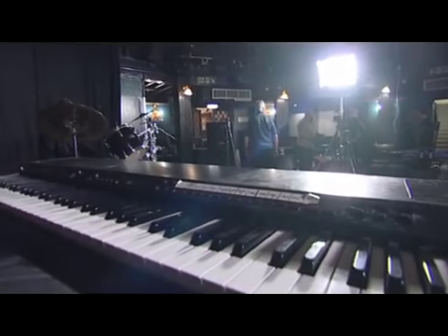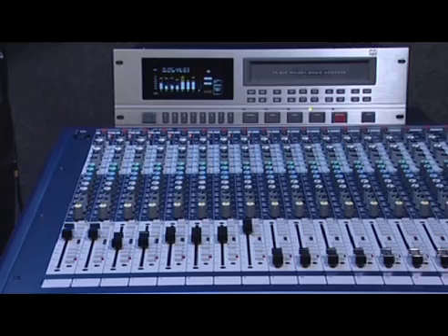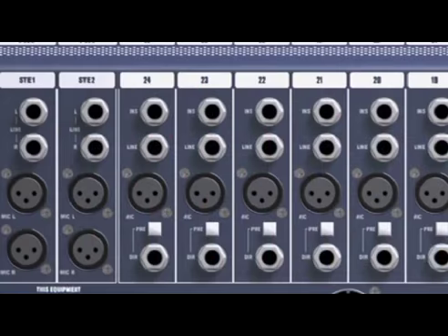Most instruments that you can't hear at all unless you turn them on have line-level outputs, and so do CD and mini-disc players, DAT machines and wireless microphone receivers. Mono outputs can go straight into a mono-line input on the mixer. You can plug stereo line sources into the left and right inputs on a stereo channel, or into two adjacent mono channels, as long as you pan them hard right and left.